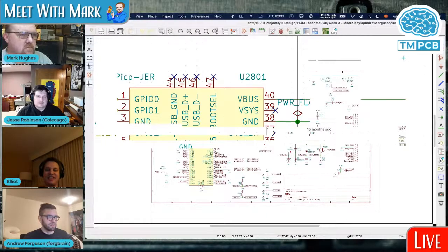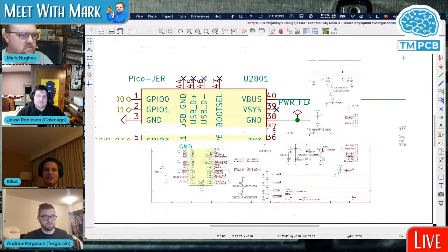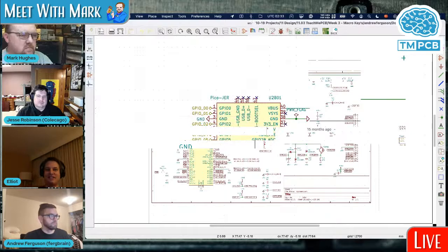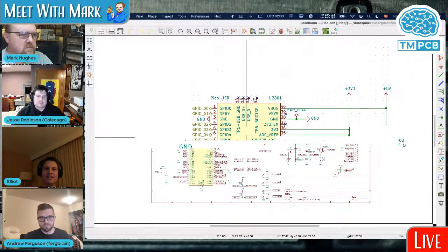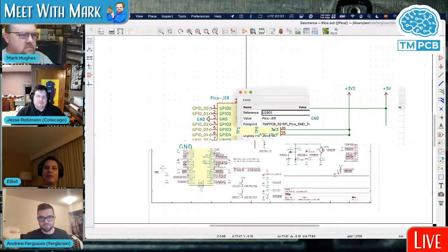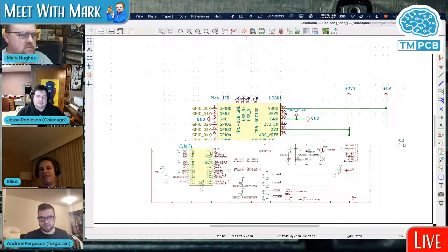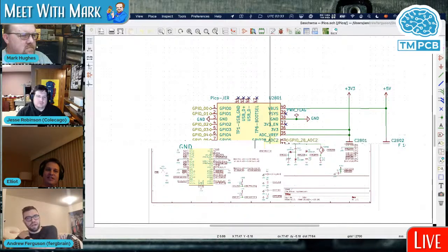And in this case, I think I found that with the Pico because it doesn't seem like the symbol has internal connections. So, for example, connecting ground to your USB ground, whatever, only really works for pin 3. It doesn't automatically make pins 36 and the rest of them. I feel like KiCad doesn't understand that they are also ground.